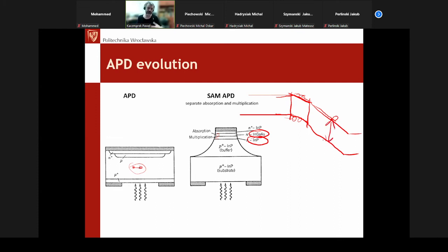Greater band gap energy also means the creation of these dark current carriers is much less efficient, because creation of the dark current components is mainly because of the thermal effect. The smaller the band gap is, the higher the dark current will be.